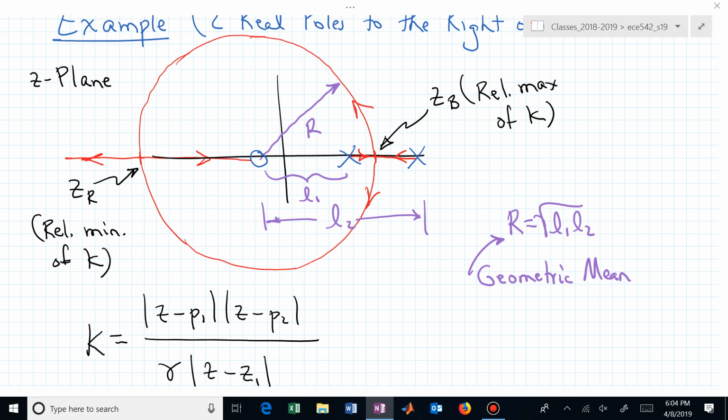It's bigger than what we had at the breakaway, but I said these are relative mins and relative max. Now, what did I just say? 16.7? I crank it up to 16.8. Now what do I have? Now I have 2 real unequal poles, closed loop poles. One is moving towards the 0, going to the right. The other one is going off to minus infinity.